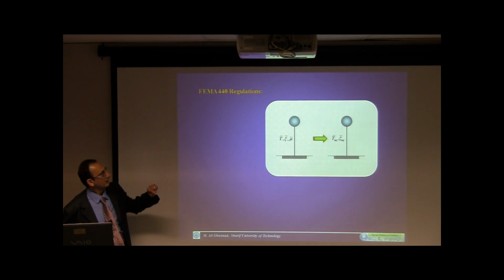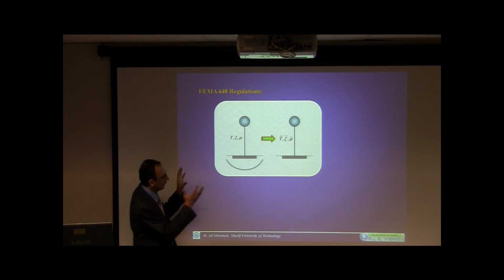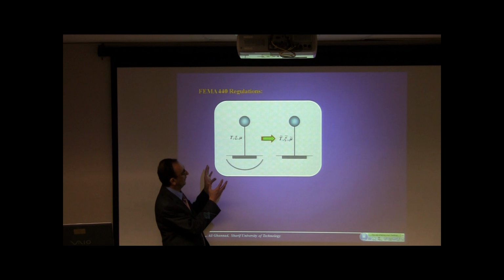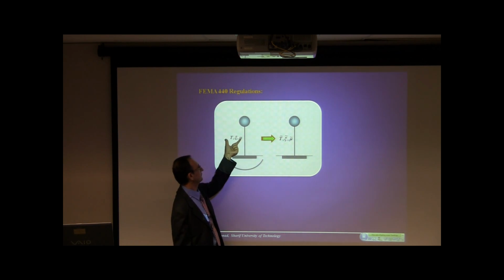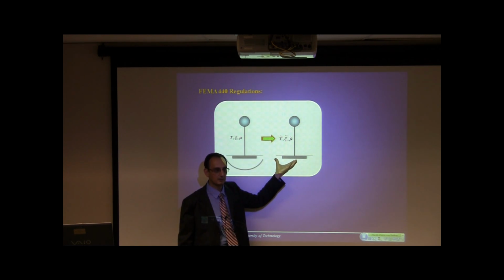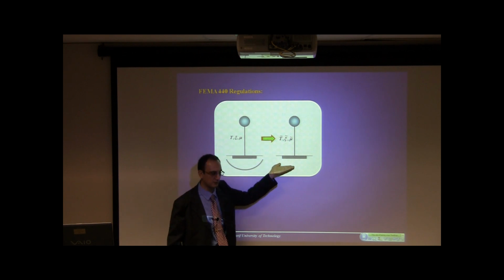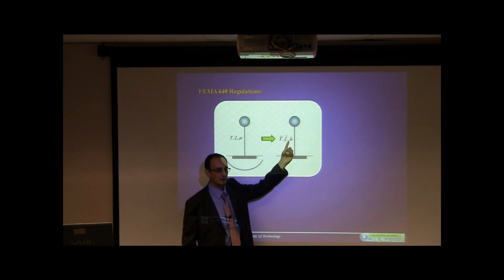And FEMA 440 used this concept and combined it with a well-established approach, changing a soil structure system to an equivalent fixed base structure with equivalent period, equivalent damping, and equivalent ductility.